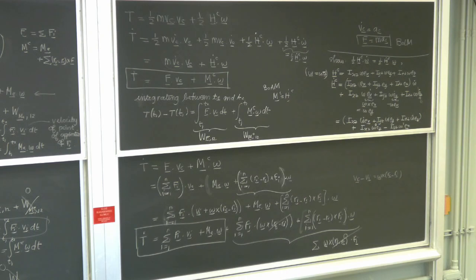We have the wheel. The forces acting on it are the weight, and then the normal force and the friction force. Okay? The weight is conservative, right? What is the work of the normal force during the motion of the wheel? Why is it 0? It's rolling without slipping. So what's the velocity of the point of application of the normal and friction force? Right, so Vp is equal to 0. So the work of the normal force is 0.